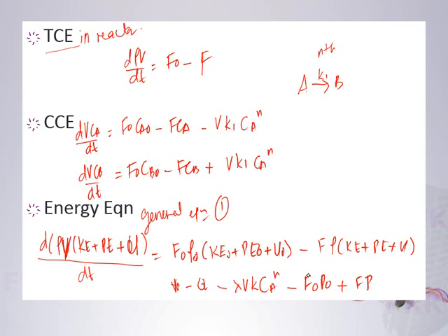After that you treat all this. Plus minus, this is not a bracket, we have already opened up the bracket. Right? Don't get confused with that, or else you're not going to get it. Then we cross. We assume the shaft work is 0 and so on. Then we're going to get the final equation, rho V CP dT. Let's not separate the volume. The densities and the CPs can be considered as constant. Rho CP dVT on dt.